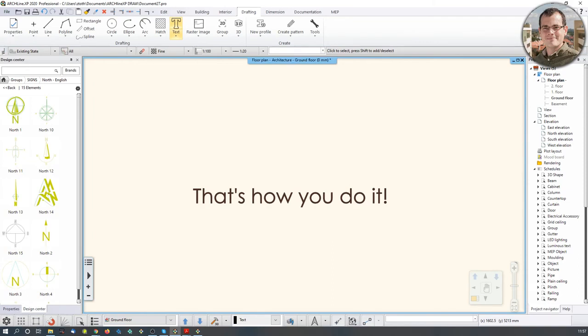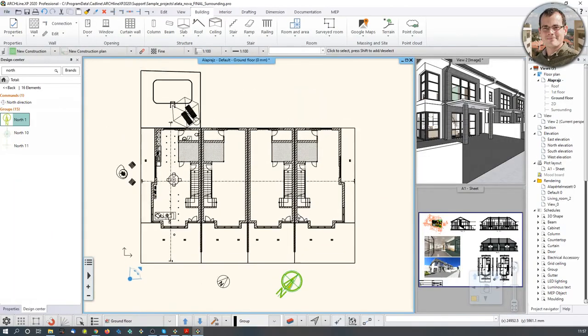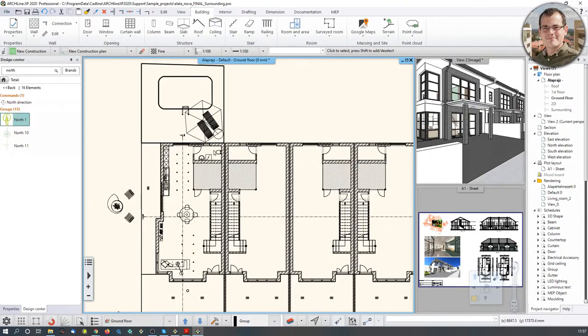About this, can the text of the floor plan for the scale not be linked to the chosen scale in the output? Well, it depends where you put the text, because if you put text into the original floor plan in an actual scale, then you have to scale that down as well in the plot layout. If you want to have a font which is the actual perfect size on a layout, then you have to copy the style, resize it, and save it as a style, as a font style customized for plots.